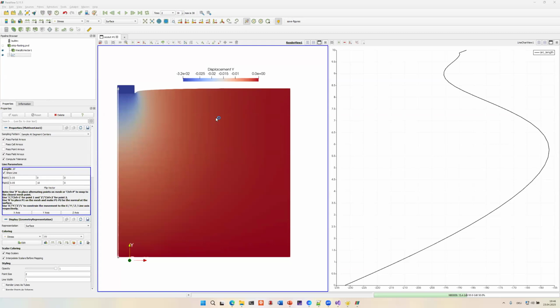So you could model until a certain deformation occurs, and then you could build that model, the geometry, load that in GID again, remesh it, and then start the simulation from that stage on, because you can read in initial states, and you could read in old states, for example, but that is a very manual approach. And yeah, so for an automatic approach, we are currently working on that in a project, and I guess that it will be ready in 1.5 years or 2.